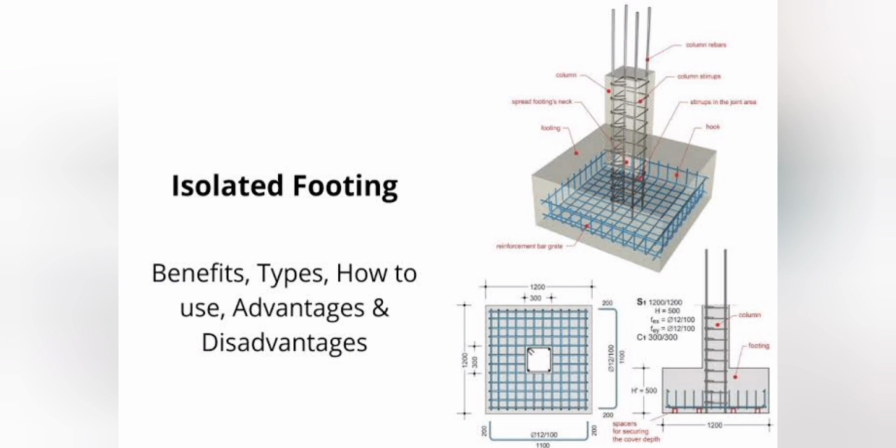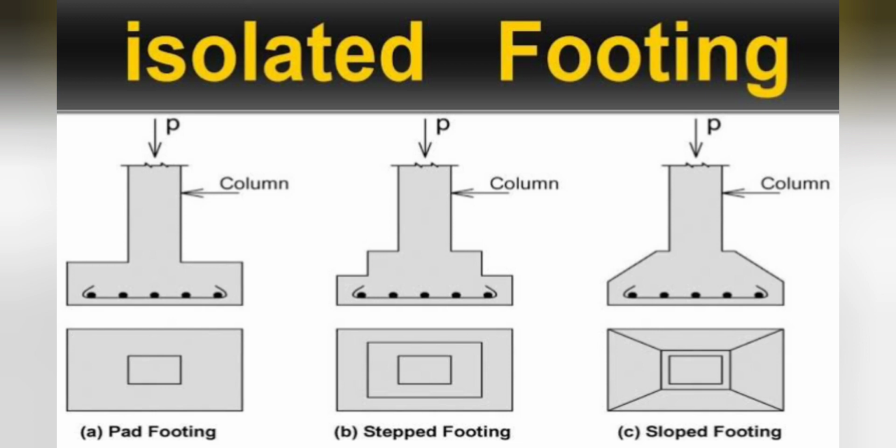Last in shallow foundations we have raft or mat foundation. This type of foundation is provided when column loads are heavy or safe bearing capacity of soil is very low. These are special cases of combined footings when all the columns of the building have a common foundation. Raft can have local thickenings or drops below columns if the thickness of raft is insufficient for shear stresses. This ends our shallow foundations.